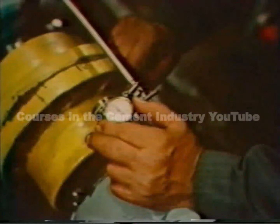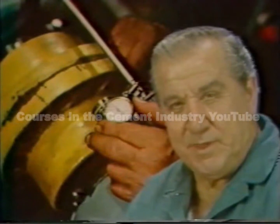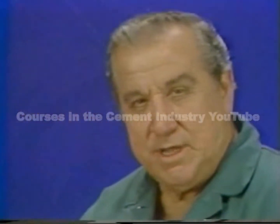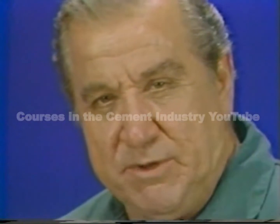By properly mounting the dial on the shafts, you can use the motion of the plunger to measure misalignments. There's a lot to see concerning this procedure, and I think it'll be easier to understand if we watch an alignment job. We're going to pick up a job that has already progressed through some of the preliminary steps.